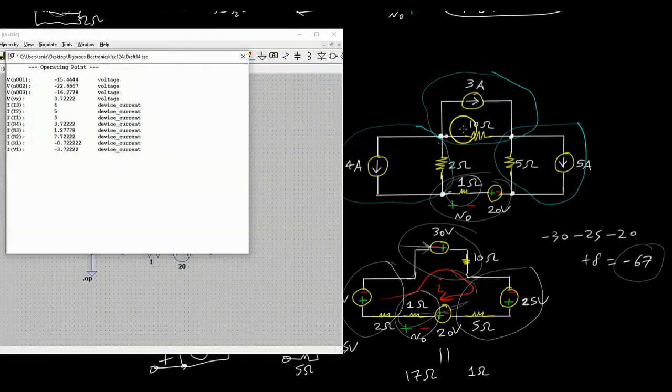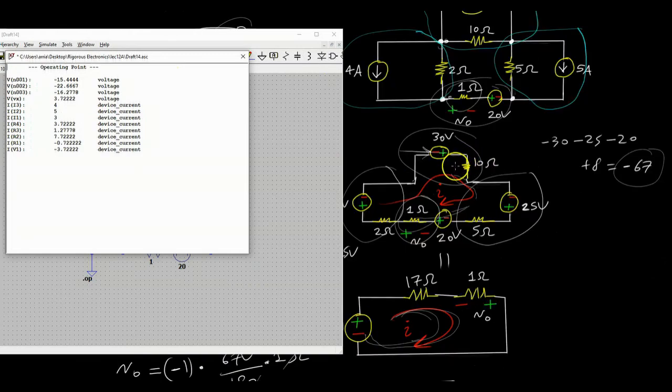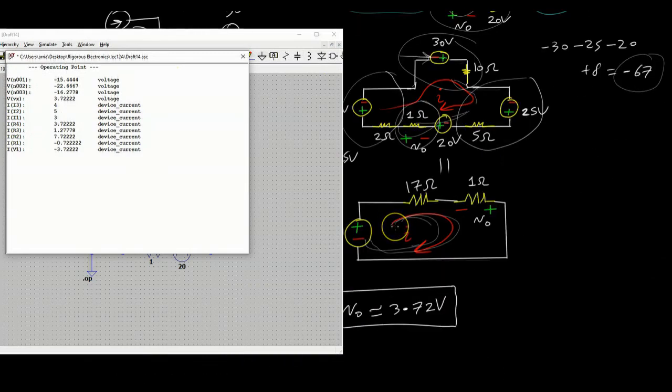Now the sign is incorrect, but that is again because of the way that resistors are defined in netlists. If you recall from the earlier lectures, I believe lecture 6A or B, when we talked about LTspice and netlists, resistors are defined as the end point and then the initial point, and so the negative sign has to do with that in this case.